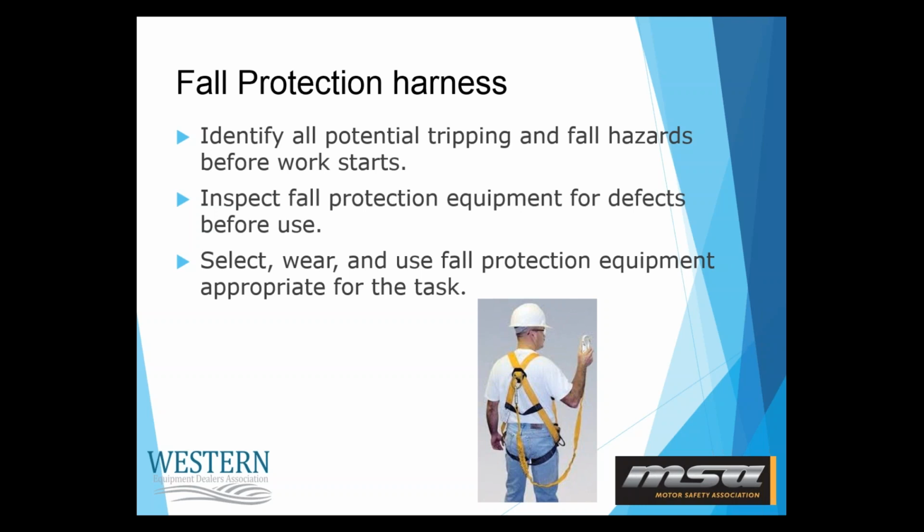But as we look at the harnesses, you want to store them in clean environments and maintain them so that they're clean, ensure that the labels are clearly visible, and look for any types of damage when you are inspecting your equipment. Contact that supplier because they can fix you up with the correct size of harness that you need, and ensure that you are using it appropriately. Some suppliers do offer fall protection and fall awareness courses. On our website, we have a fall protection and fall arrest free webinar, which will give you some tips on this topic.